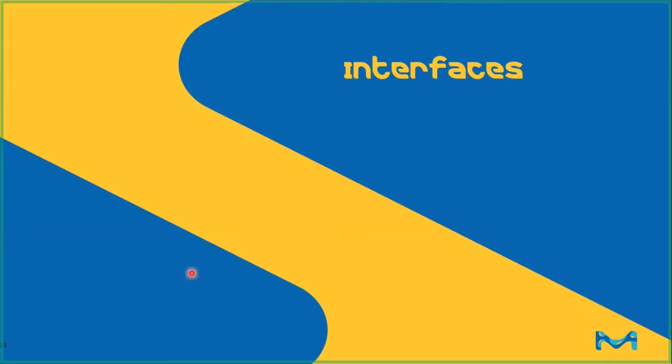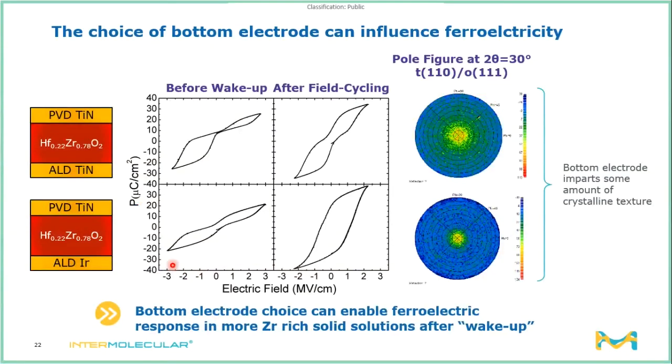So building on the fact that we can see how important interfaces are on affecting the crystal properties in the systems, next, I want to take a look at a couple of ways that we can influence the ferroelectricity of hafnium oxide outside of the ferroelectric material itself. For this particular experiment, we're looking at a material that leans a little bit more towards the zirconium oxide end of that hafnium-zirconium oxide blend. We have a fully blended film, but again, it starts to lean more towards zirconium.